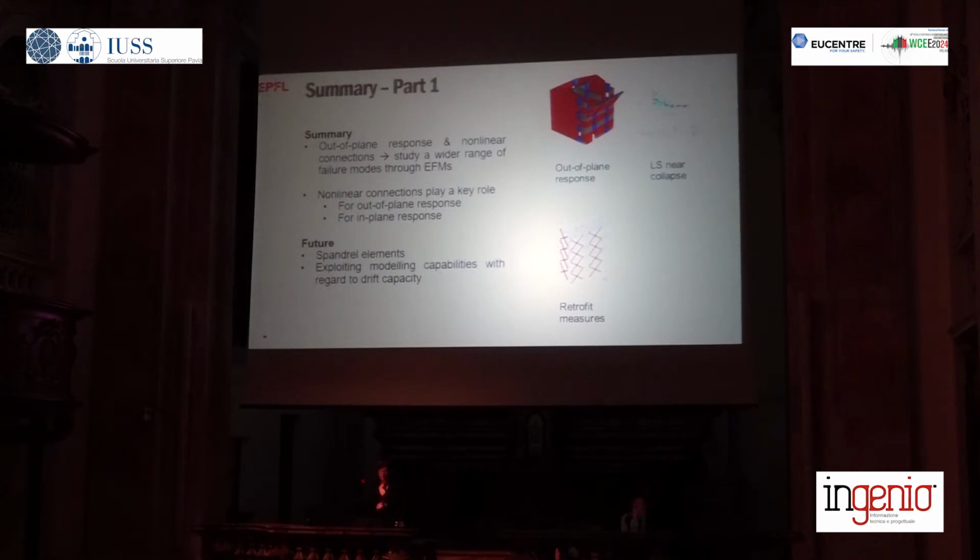So basically showing that with that augmented macro element model, we can really capture also the out-of-plane response. It's important to also include the nonlinear connections in order to activate these out-of-plane mechanisms, and it really allows us to study a wider range of failure modes through equivalent frame models, which are really so widely used in engineering practice.